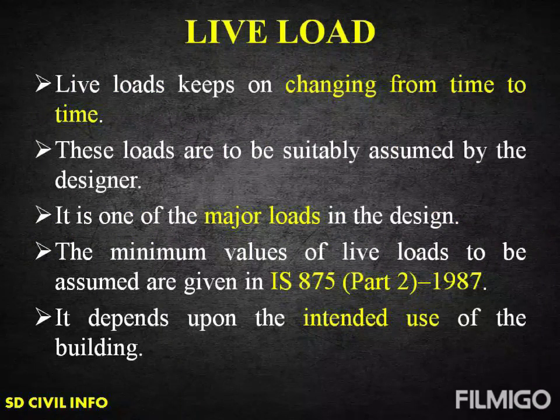These live loads keep on changing from time to time and are to be suitably assumed by the designer. Live load is one of the major loads in the design process, and in IS 875 Part 2, the minimum values of live loads to be assumed are given in detail, and it depends upon the intended use of the building.